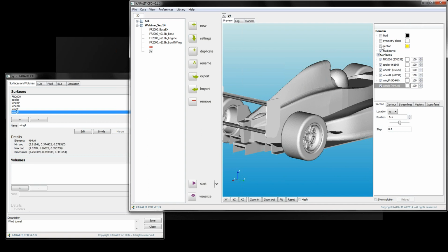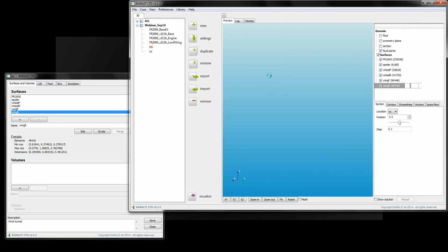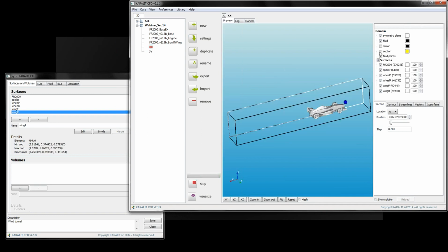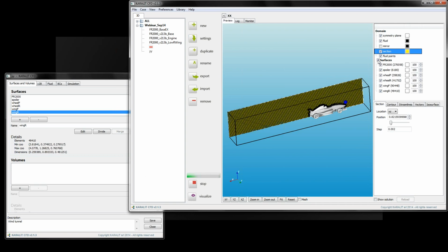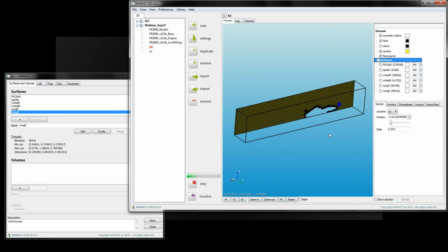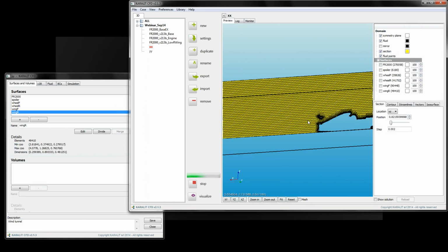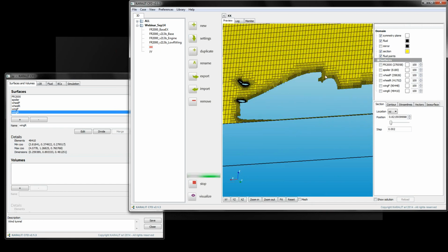Additionally, it's a Cartesian mesh, but in an immersed boundary framework. If I show you the mesh on this case that we are running, you're essentially taking advantage of immersed boundary and applying the boundary conditions of the surface at exactly the right positions, but you're not actually generating a body-fitted mesh, which is very time-consuming.